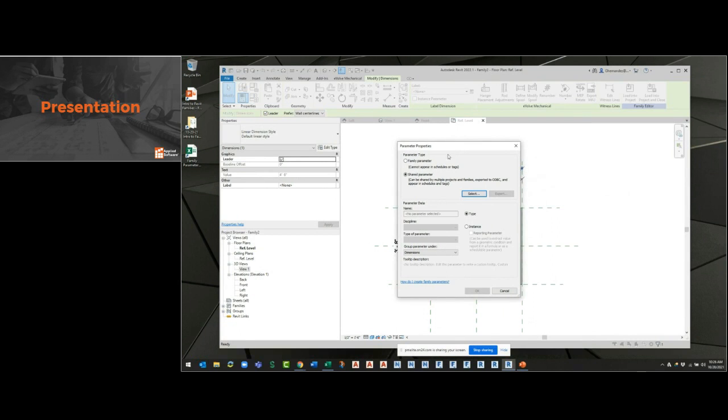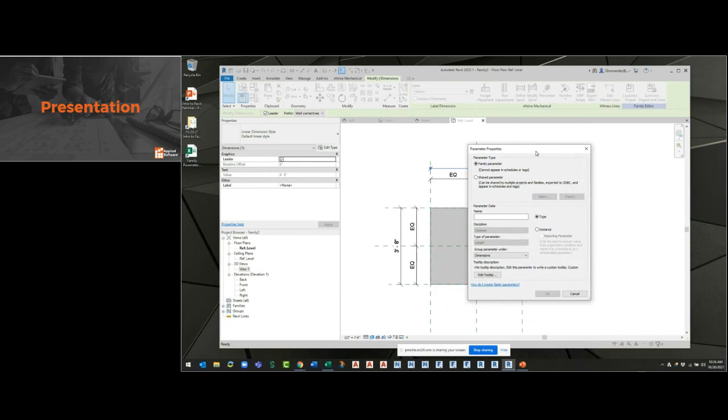Now, this is best practice with the shared parameters file. I'm going to just create them in this family here as family parameters, so you can kind of see what the difference is. Okay? So this one, I'm going to call this, just leave this all caps, unit length. Now, the difference here on the right between a type and an instance parameter is this.